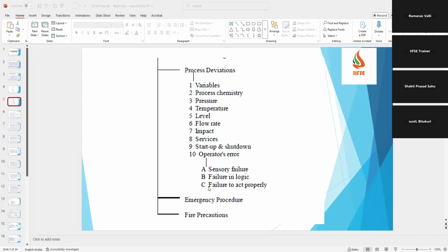Okay, so first the communication is the alarm. So how does the alarm rise? Who will activate the alarm? When they receive the information from the work area, security or EHS personnel raise the emergency alarm. Also we already have manual call points in the work area, where they break the glass and the siren comes.